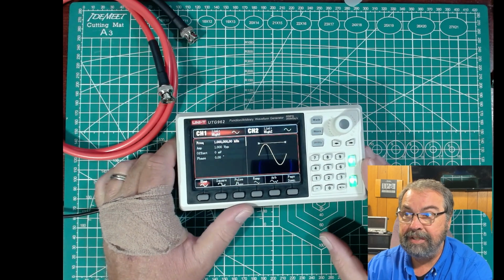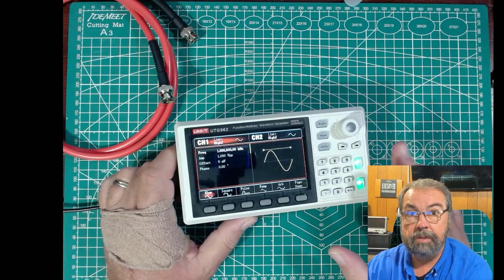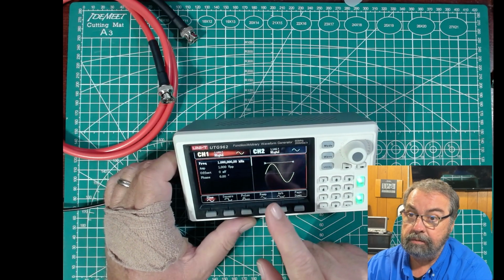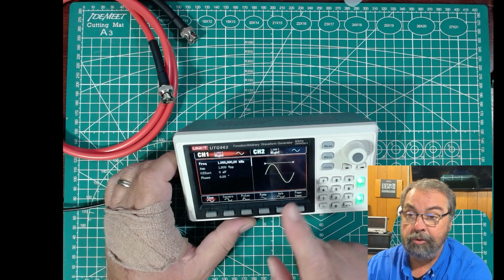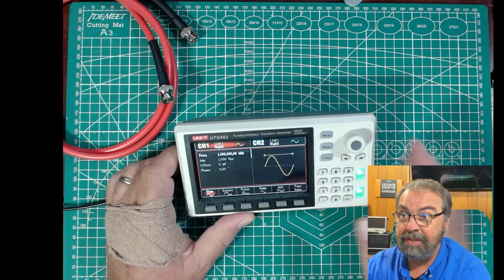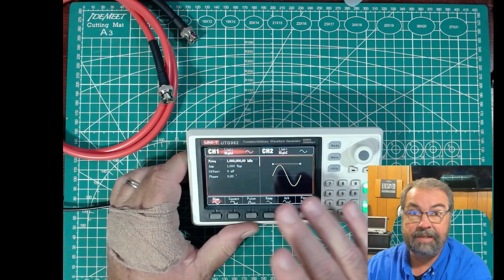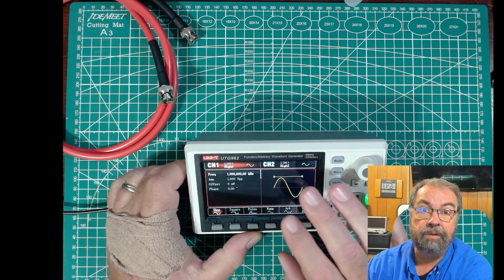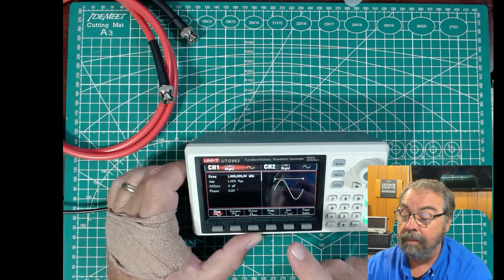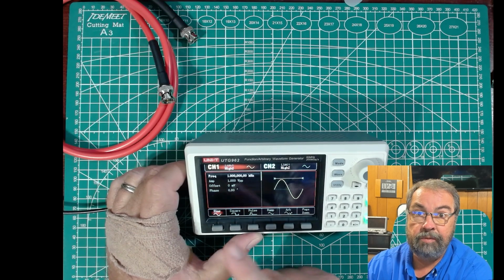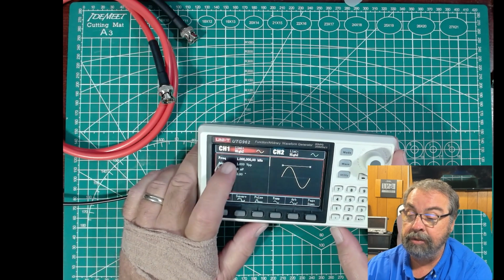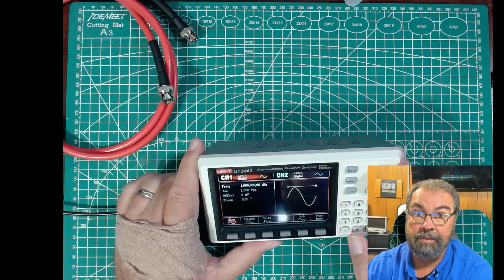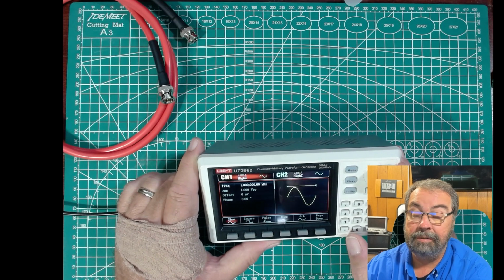This is a Uni-T UTG962 signal generator, arbitrary waveform, function generator, whatever. It is 2-channel, and I have both channels set up the exact same way. You can see here on the screen, they're both set for high Z, that's high impedance output. The signal generator can output 50 ohm impedance signals, but for our test, we're using high impedance. Both of these channels are set up for 1 kilohertz signal. I know that looks like a trillion or something. It's 1 kilohertz. It's the way this thing displays numbers in kind of a weird format. It is a 1 kilohertz signal.